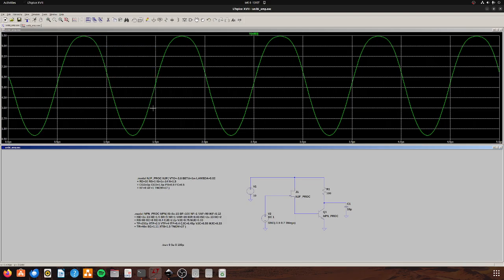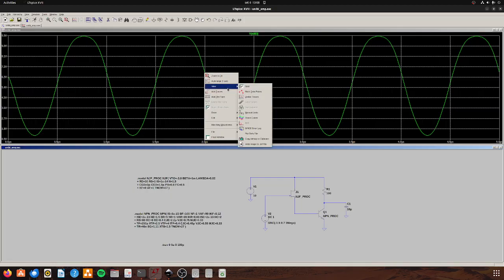Now, one of the largest problems of these amplifiers is that the gain and DC point actually change a lot with temperature, since it doesn't have a feedback loop. It needs a feedback loop in order to define this DC voltage, and the gain is always open loop. It's difficult to fix the gain here to a certain value. This is the most important problem of all these amplifier circuits.